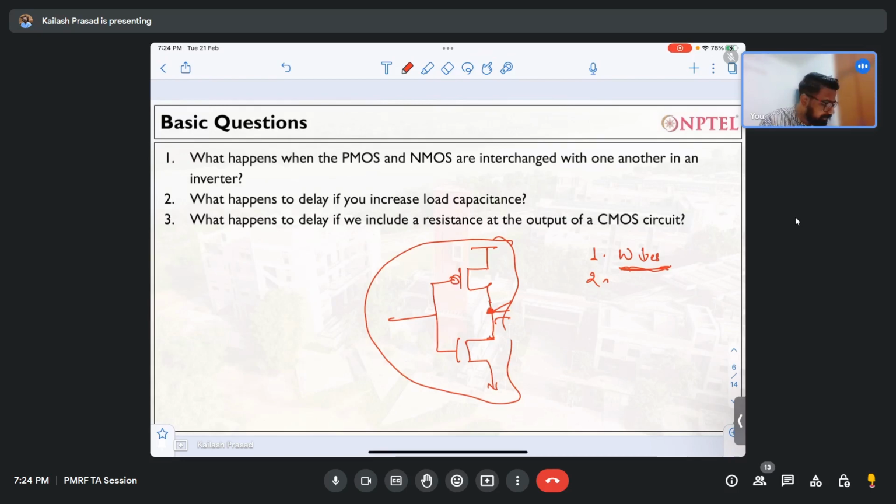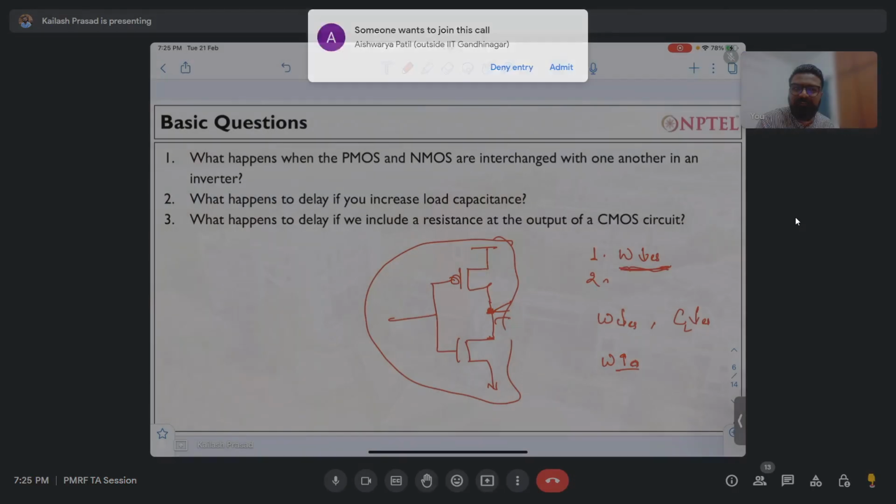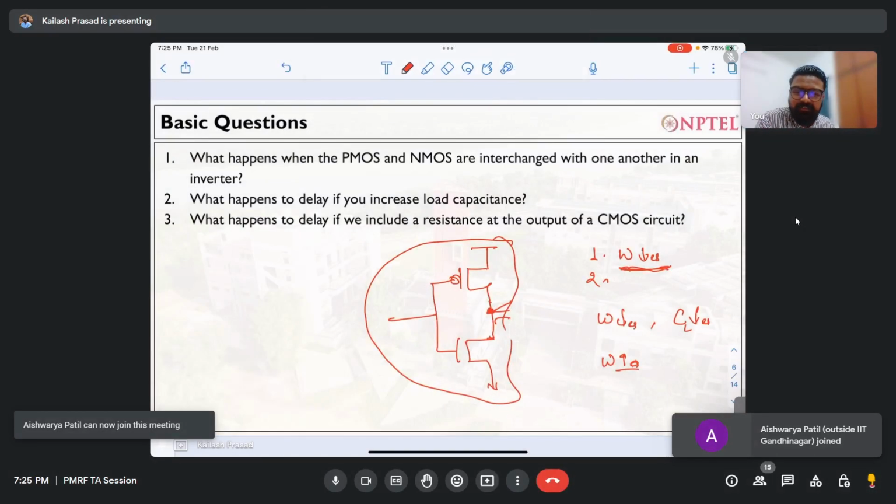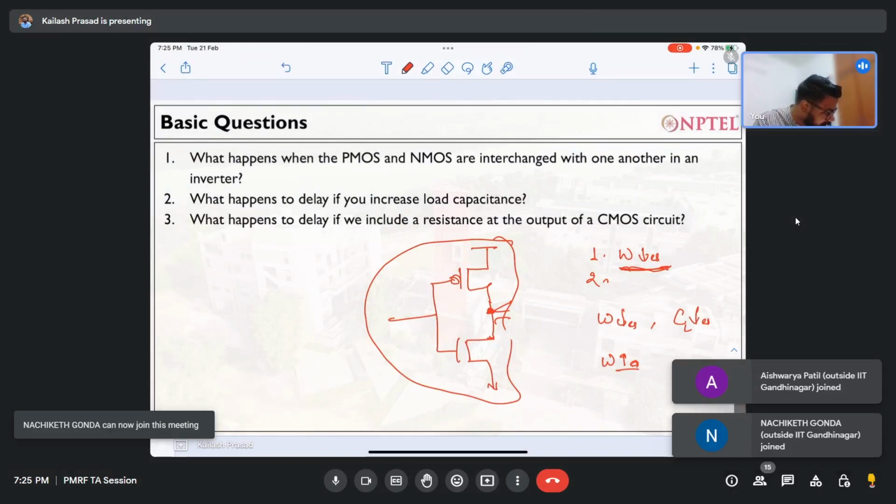I agree that if you reduce the width, the capacitance will go down. Increase W, sorry, increase W. You're saying increasing W. Okay, I have an alternative argument. Why should I increase W? By increasing W, we have a smaller resistance. Excellent. Yes, so R will go down.